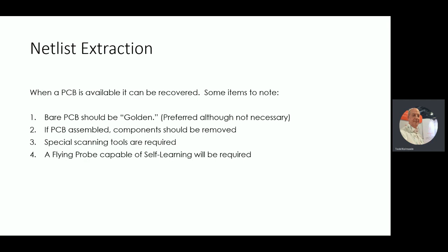So once that is done, then we actually have a net list, and we can send it back to the customer, or you can send it back to your customer or design group, usually as an IPC 356 type net list, and they can go back and run it through their software, and they can actually regenerate photo tools, Gerber layers.